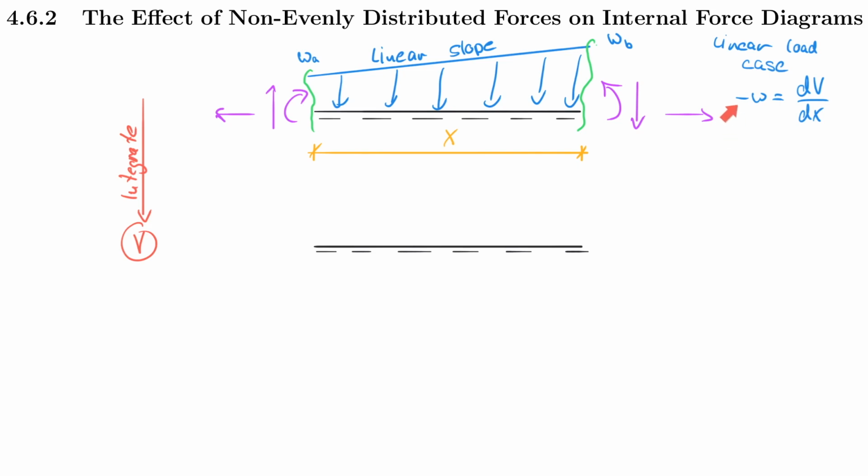So now it becomes a little bit tricky because we have the minus here, but there's nothing that we cannot solve. We can, however, use the similar logic and move from this sloped line to the shear force function here. And to do that, let's first indicate again that this is a cut system and that now I have to end up with a parabolic function, right? Because again, here the load case is linear, and I now need to end up with a parabolic function. And that parabolic function needs to reflect this slope. But now be very careful, because this slope here once again describes just the value of the slope of the shear force. So I say that again. This value here describes the slope of the shear force function at that location.